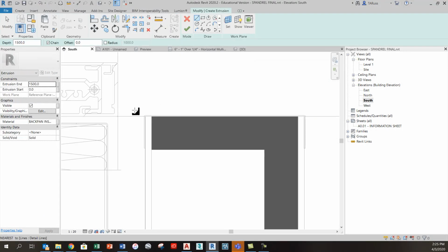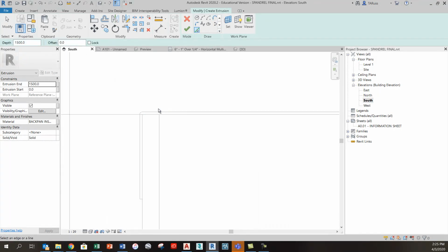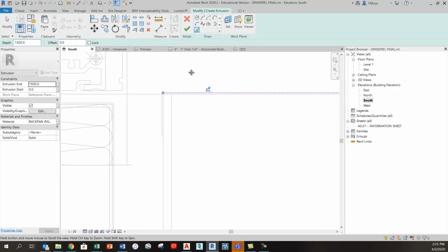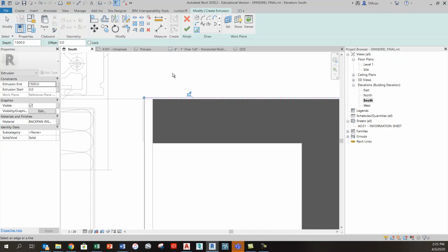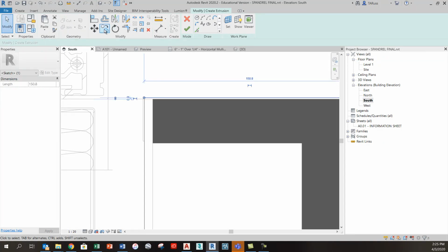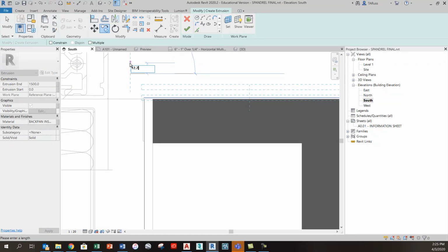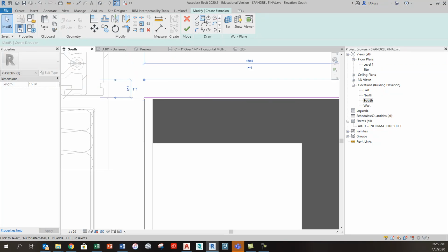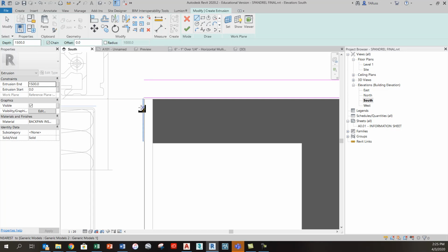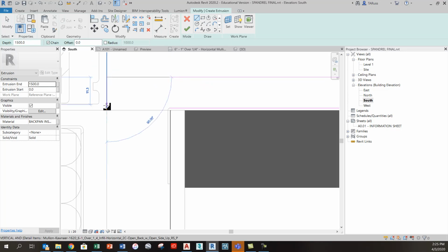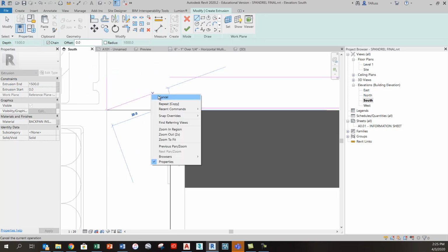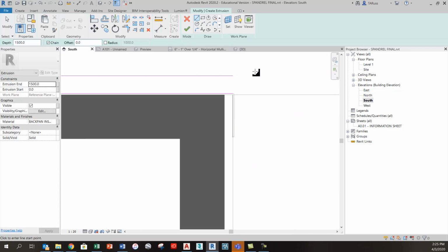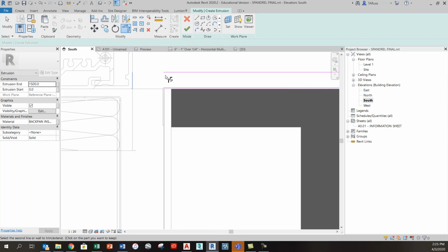And as I said, now I'm just going to create maybe something that is a 1/2 inch, 12.7 millimeter just millwork piece. So I will just take that line and copy it up 12.7, and just use the regular line tool here, and maybe have this come right to the back side of the mullion, and then I'll have something out here that maybe has a bit of a fillet to it. So I will just use my trim extend to corner tool to wrap this up.